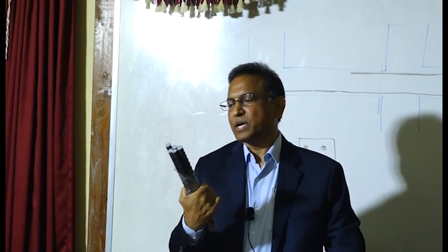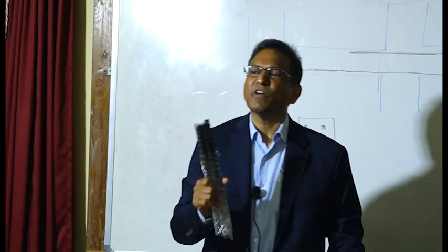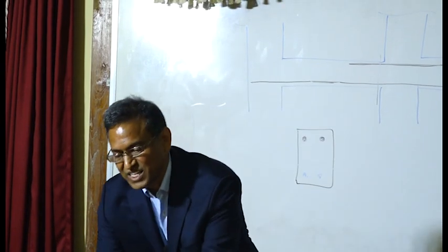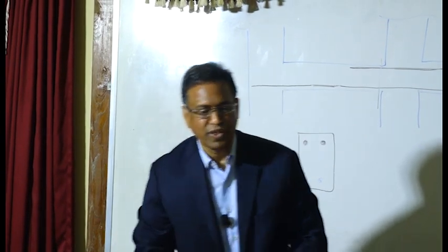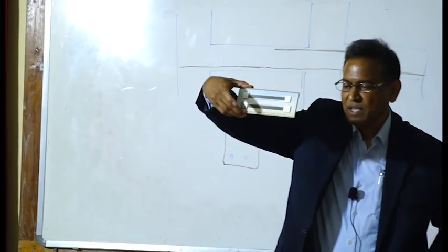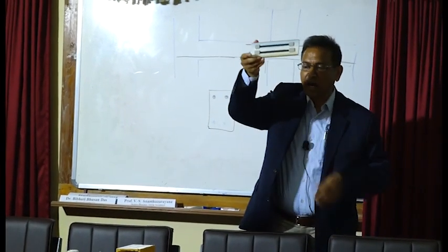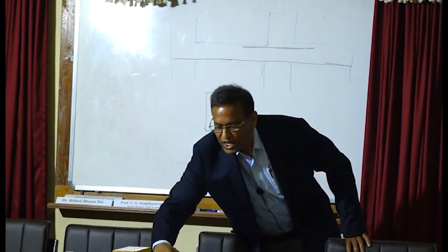and vinyl ester or epoxy bars. So epoxy is cheaper than vinyl ester for sure, but performance-wise, vinyl ester is slightly better. It's more expensive for sure. And you have carbon strips. You can glue these to the underside of the beams and stuff like that.